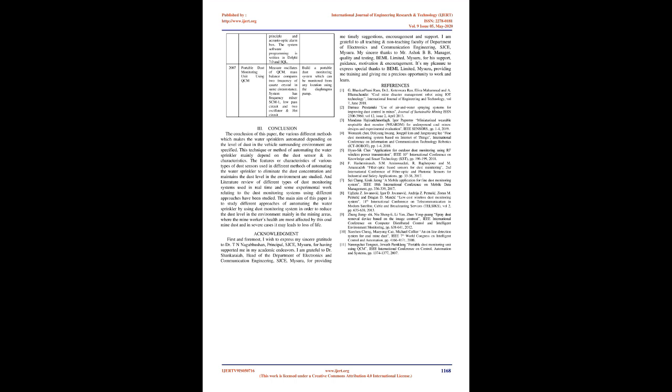2008: An online detection system for coal mine dust. The system consists of computer, signal converter, powered network substation and a local control system. The last item of the entire components setup has a controller, infrared induction switch, electromagnetic valve, water flow switch, dust concentration sensor based on scattered light. Designed an online method of detecting coal dust concentration, having features like online processing, slip-weighted average sampling along with bilinear fitting and automatic correcting of K values, and an acousto-optic alarm box. The system software programming is written in Delphi 7.0 and SQL.